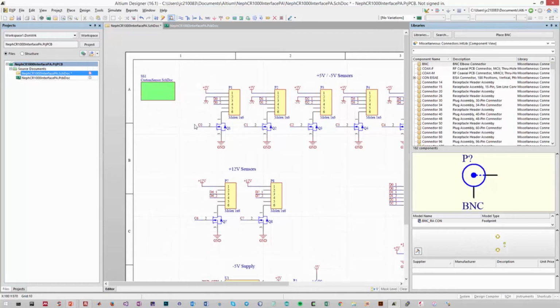So in the case of our circuit, we have one input, this C0 signal, which will allow us to turn the sensor on and off via a switching circuit on pin 6. And we have two outputs for our custom sensor, D01 and D02. The 5-volt rails, positive and negative, are internal items that will not be outputs or inputs. They will be constant supply. So our circuitry here is basically going to exist inside of this green box, and we do that via creating a new schematic file that this will be passed into. So that's creating a sheet symbol.